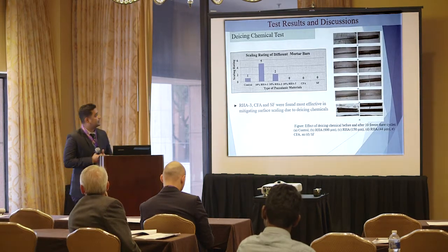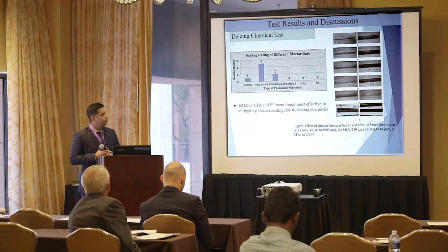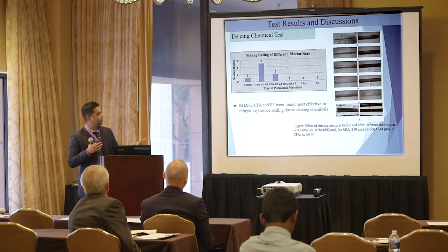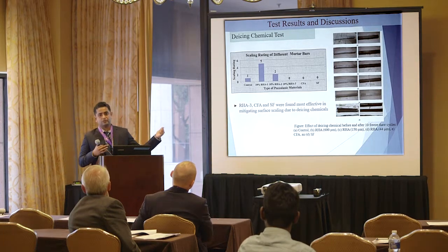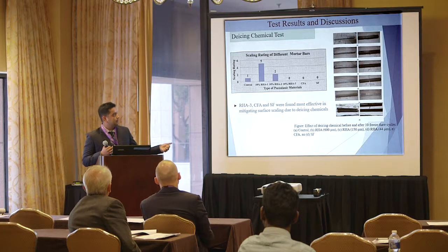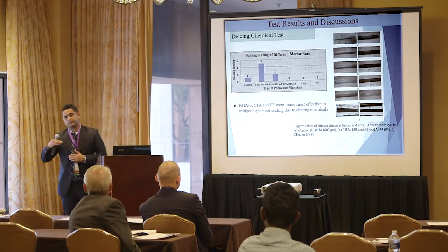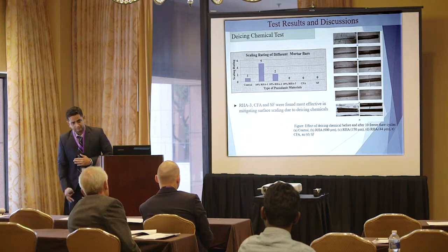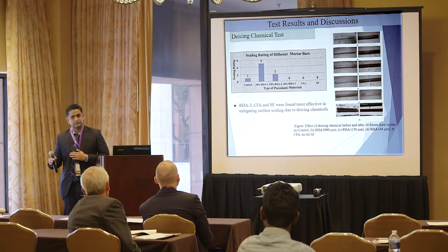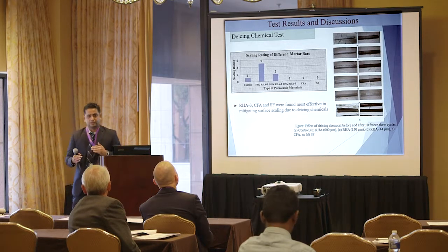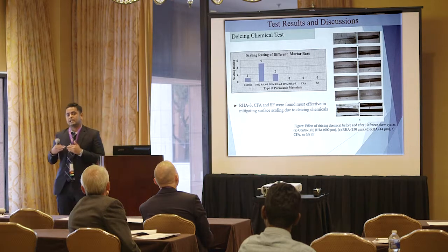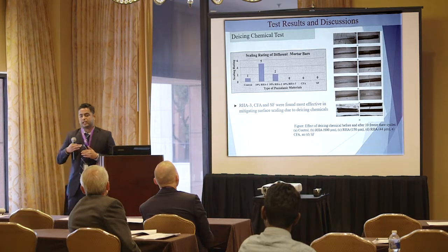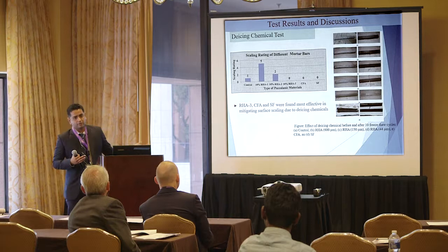And this is the de-icing chemical test. As I already told you, I did this for the mortar bars, but the specification is for the whole concrete slab. I also put these mortar bars through freeze-thaw cycles, 18 hours at freezing temperature and the rest of the day in thaw cycles, in the presence of calcium chloride to see how the de-icing chemicals affect these mortar bars.